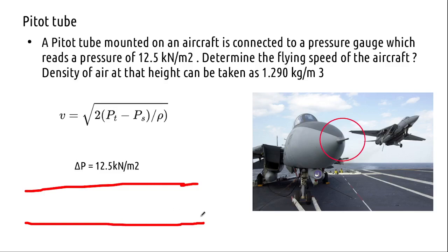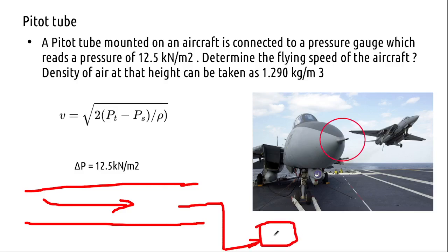throughout the building. So if you want to measure the velocity, air velocity or the fluid velocity through this, you have portable Pitot tubes, something like this bend. This is the fluid flow through this pipe, and you could connect it to a portable pressure transducer, which will give out all those readings, and it will even calculate the flow velocity also. So such Pitot tubes are there.